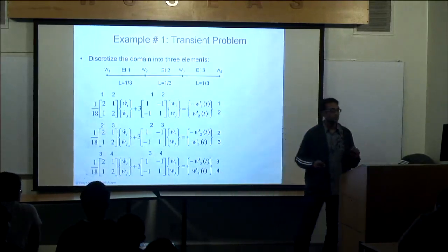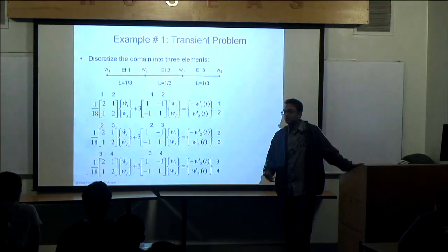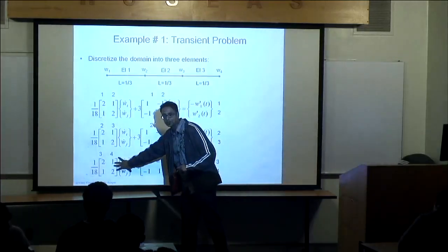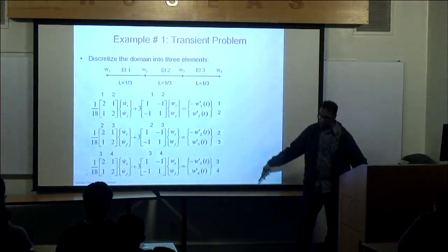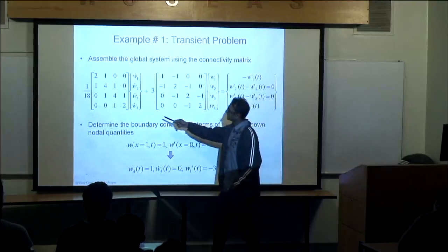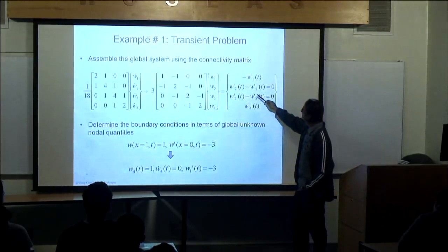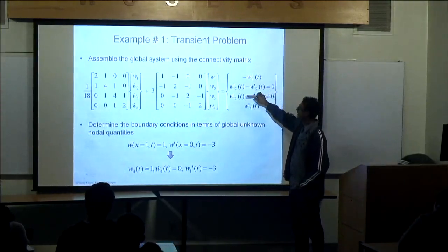Okay, excellent. So, hey, the assembly is the same process. The assembly process uses the connectivity. It's no different. You have to assemble this matrix here, which you have not dealt with before, and we have to assemble that one right there. Oh, and the forces on the right-hand side. When I do that and assemble it, this is how it looks. I have a 4x4, 4x4, and I realize here that these middle terms cancel out when I do the assembly.